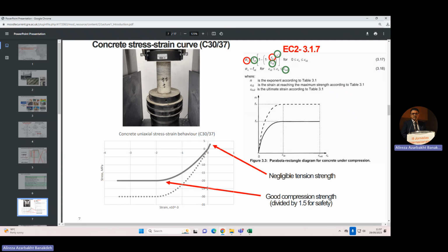But before that, why is this graph at the bottom and this graph at the top? The reason is, I'm talking now about the compression. That cylindrical sample, okay? Under the pressure, under the compression, I want to crush it. The force is compression. Because after this, I'm going to talk about tension. As a convention, most commonly, tension forces are positive, compression forces and stresses are negative, okay?